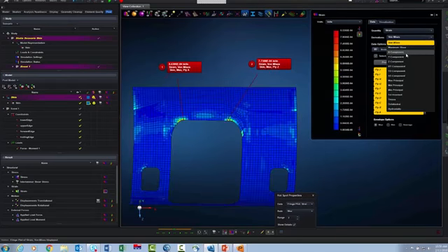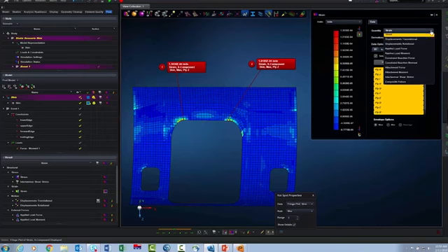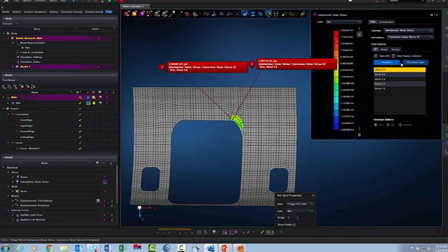Let's look at sigma x. Now the strain in the x. I can look across all if I want to quickly identify worst ply and worst location. In addition to looking at the stresses and the strains, I can look at the interlaminar shear stress, okay?